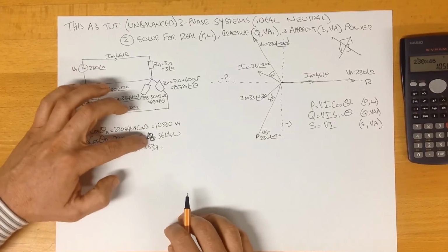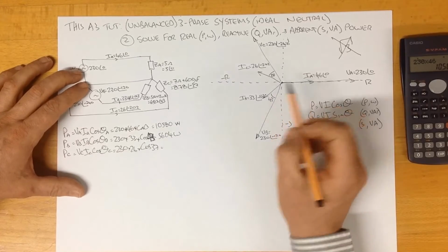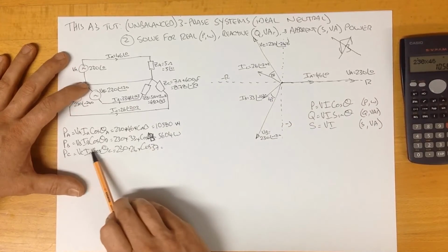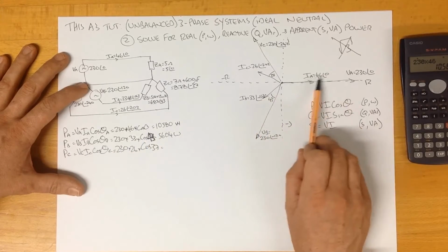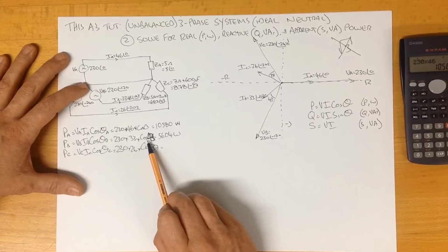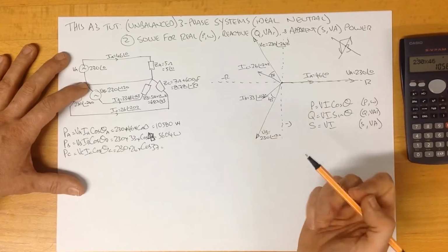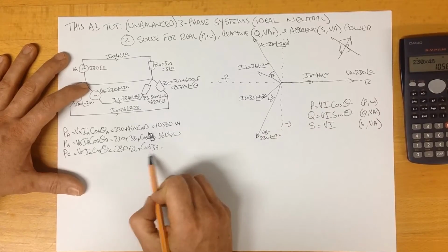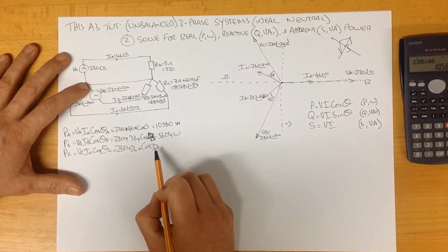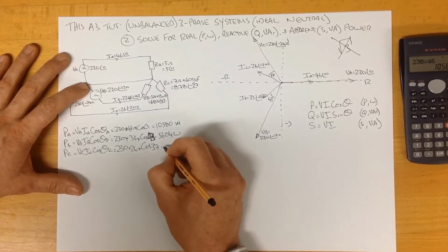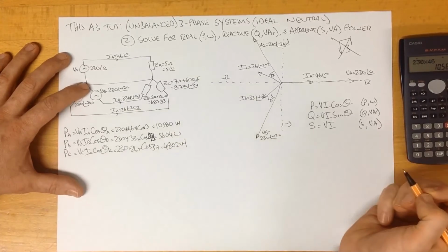Now, the subject of these degrees is an area where a lot of students make mistakes. They use the wrong angle. I've seen many exams where students, when calculating the power in phase B, have used the angle up here in phase A. That's obviously wrong. Likewise with phase B, they will use the same one, and it's simply wrong. If we calculate this, 230 times 26 times the cosine of 37 degrees, we get a solution of 4,802 watts.